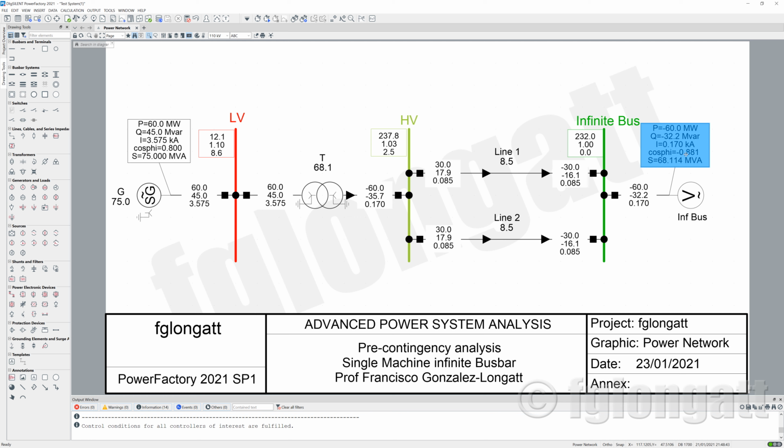When you are working with power factors, remember that that is the cosine of the angle. And when you are working with low power factors, you are going into the nonlinear region of the cosine. For that reason, small changes look small, but that is not true. It must be 0.80. Anyone making this mistake, this is a terrible mistake.